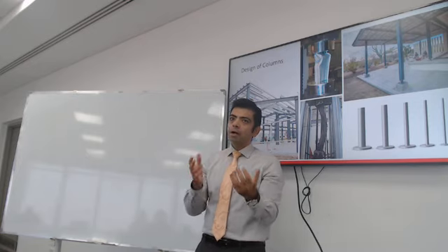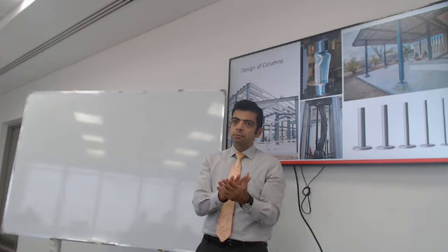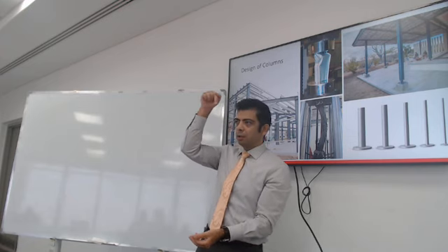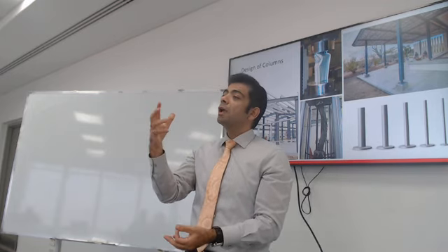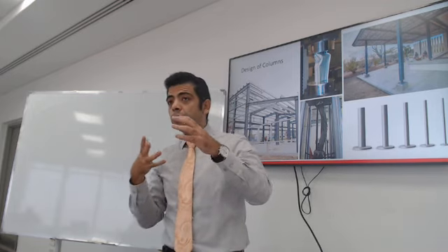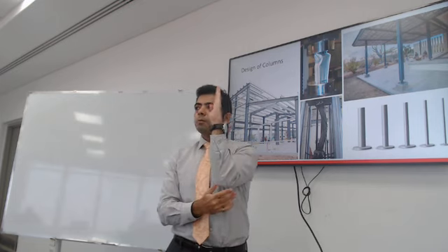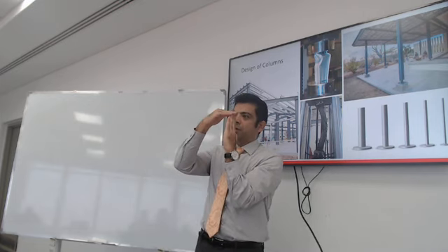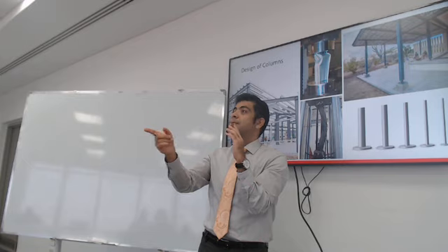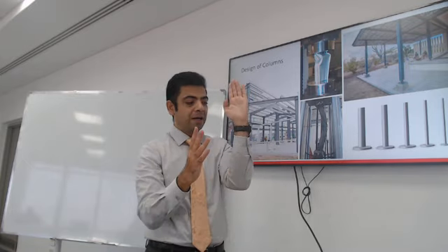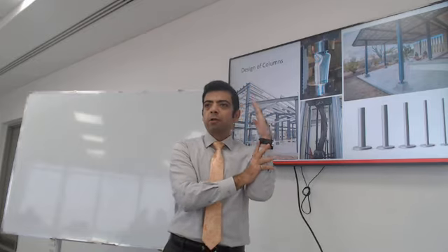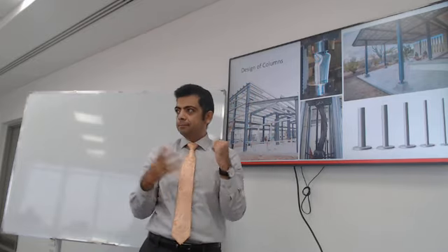So what would cause bending on a column? Axial load is the load on the column, so we would get that. The shear force could cause bending. What would induce shear force on a column? A column is vertical and it's supporting vertical load. Any horizontal force. I like that very much. So if you have a column that is supporting any horizontal load, that will introduce bending, right?